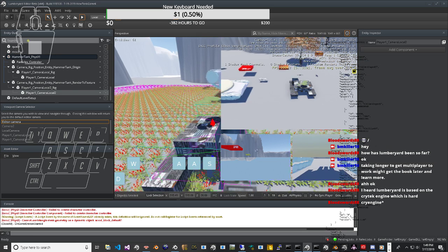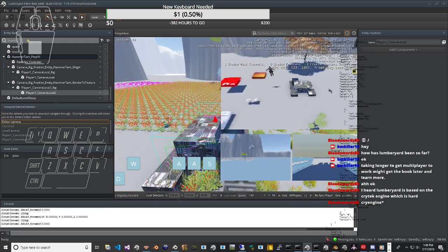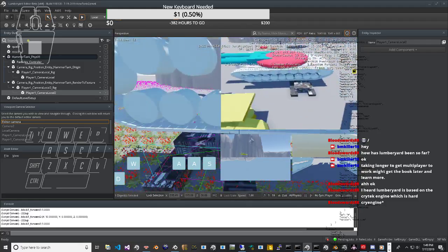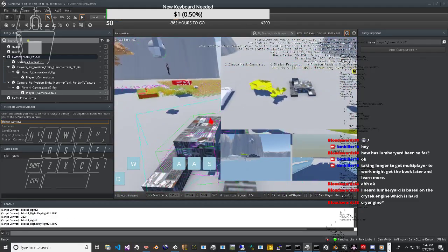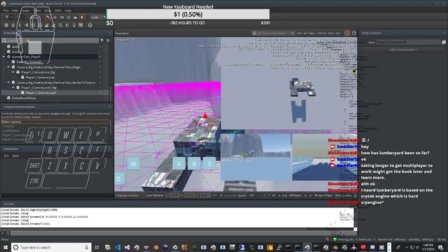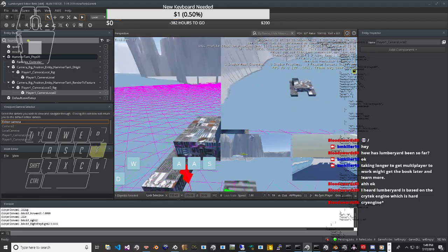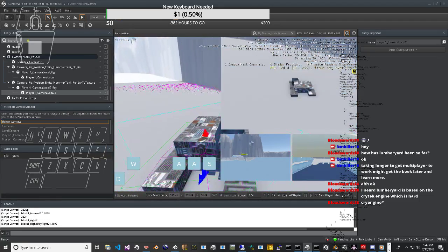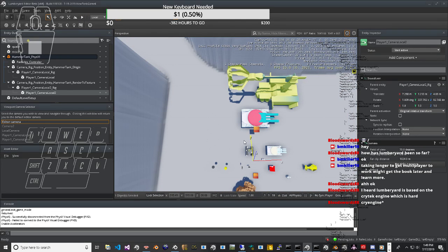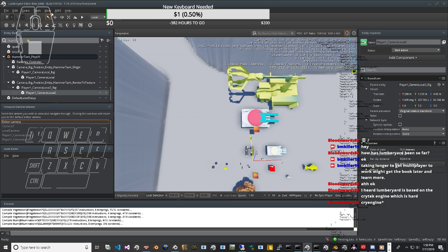As before, we get B from a product, albeit one of greatly different form. Where the camber term is the absolute value of the camber angle, that is, a positive number no matter what the sign of the camber. This gives the following. Almost done, include and sneak in an additive correction for plysteer and conicity, which we'll leave undefined in this article. To arrive at the final formula. This form is almost identical in form to the longitudinal version of the magic formula. The individual subcomponents are different in detail, however.